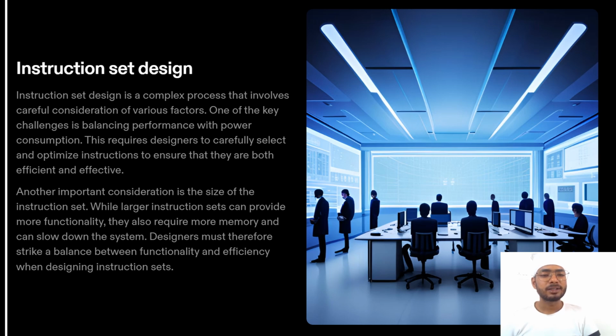Another important consideration is the size of an instruction set. While large instruction sets can provide more functionality, they also require more memory and can slow down the system. Designers must therefore seek a balance between functionality and efficiency when designing instruction sets.